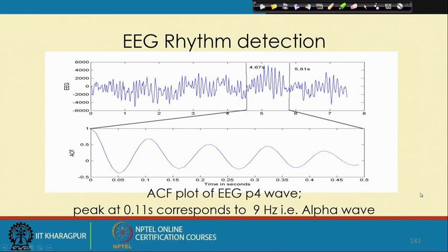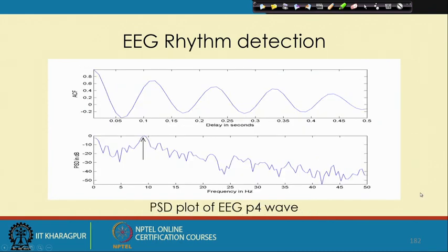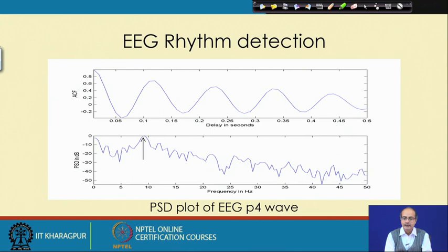Now, we are repeating this, and we would like to compute the PSD. We have taken the frequency plot and computed the frequency amplitude. Why are we talking about the amplitude specifically? Because we know that while taking the Fourier transform we are using e to the power j omega, so a real signal can give a complex output.